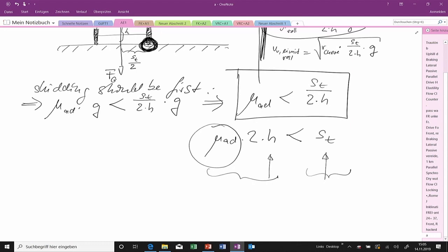And the same could happen with a vehicle, because around the roll axis, we have a moment of inertia. There's distributed mass in the vehicle. This creates a moment of inertia. And we have, of course, a spring, because on the left side and the right side, the wheels are connected to the vehicle by body springs. So there's elasticity. So the same as this spring pendulum could happen with a vehicle.